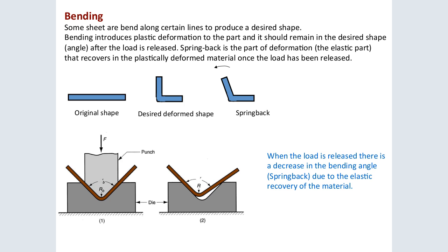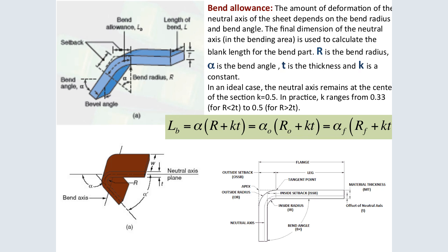So you can see dies and punches. So this is a punch, as we had talked about in punching, and the die. The die is the one that holds the metal in. So when a metal is put in between, it bends or is punched depending on the specific angle of that punch. And the die is also there to fit the exact angle that is in place.